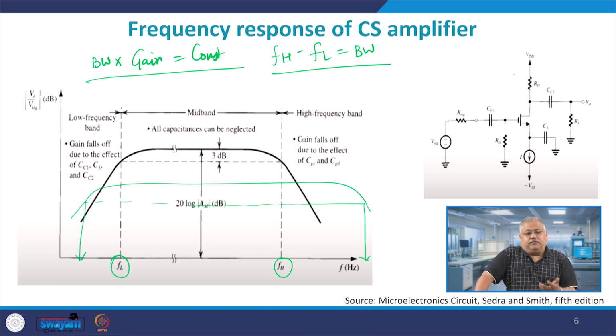Now, if you look very carefully, if the output current by input current is 1 and you are working in dB scale, then 0 dB will be the gain where output current by input current is approximately equal to 1, and any 3 dB drop from there will give you the bandwidth in terms of power. This is also referred to as the half power point, where the power has actually dropped to half its value from the mid band gain.